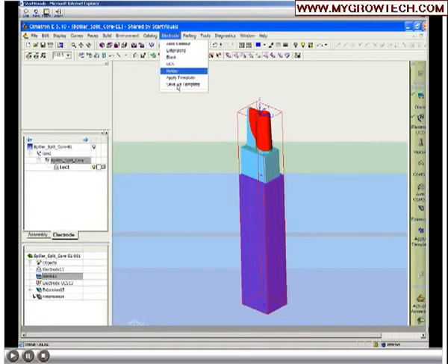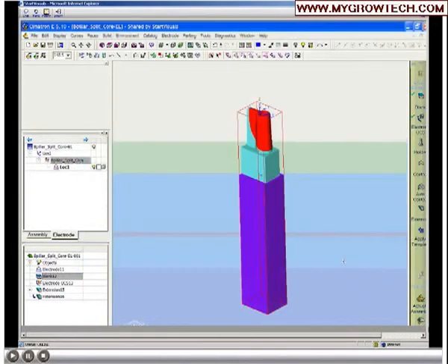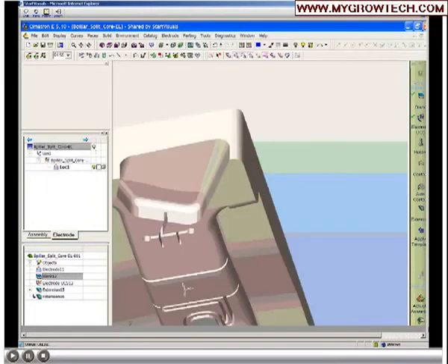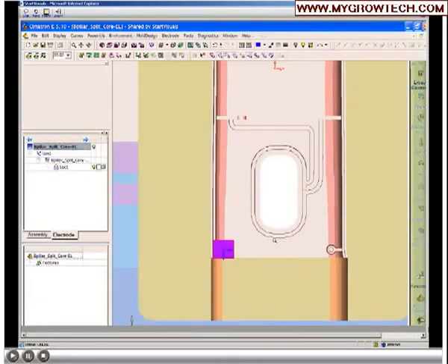Now we like what we see on the screen here, so we're going to save this methodology of creating it. It's called internal to our system. I'll call this one Trode 1, and we will save how we created this electrode. Let's use that in applying it to our, going back to our mold surface here. We'll go over to the other corner on the right hand side and pull an electrode from there.